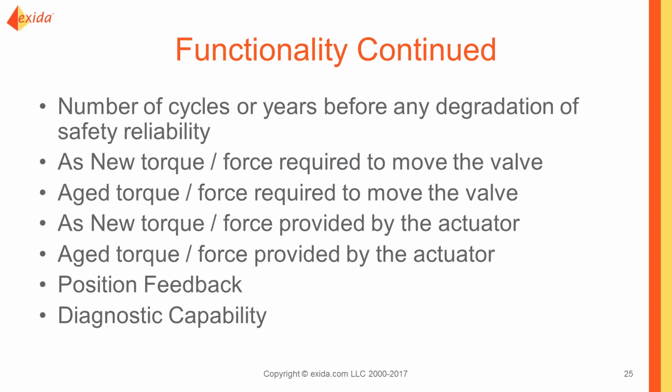Again, the torque required of the valve when it's new or when it's in motion, we need to know. We also need to know if we expect that's going to increase over time because of buildup and or lack of use. But then we also need to understand the torque or force provided by the actuator. It wouldn't be unusual to have a higher torque when an actuator is brand new. And I'll use torque interchangeably with force, but a higher torque or force output when they're brand new. And that may go down over time as the seals wear and we have a little more leakage past the seal, so we can't get quite the maximum force.